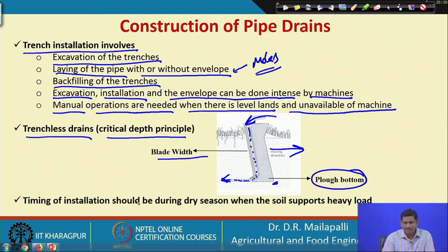So this way I already explained this figure, the cutting mechanism, previously. Mostly the installation timing should be during dry season, when the soil supports heavy load, because we will be using heavier equipment. The soil should be favorable for trafficability and also workability. Okay.